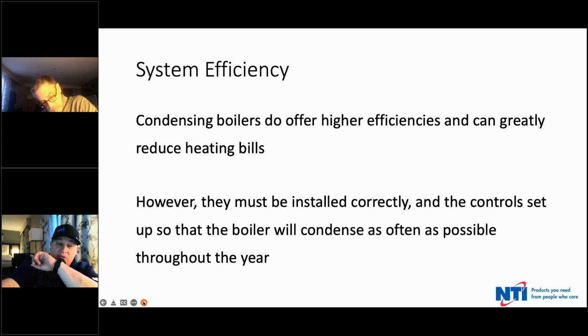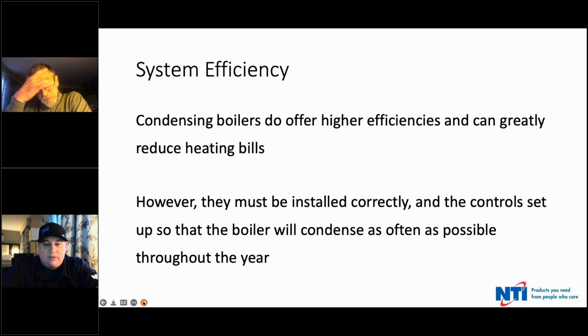If the outdoor reset and the indoor reset are hooked up, you have features to get the best efficiency, because you will be able to increase to cover your indoor temperature and satisfy that and maintain that at an efficiency rate and maintain the outdoor temperature. Great question, Kevin. Yeah, so the advantage of indoor feedback is to further refine outdoor feedback.